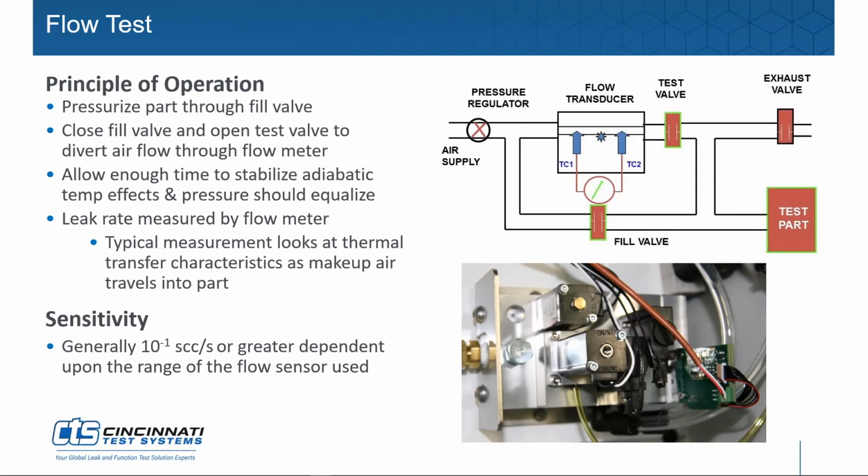And the sensitivity range of this technology is based on the flow meter range. So a flow meter that is 0.1 to 10 cc per minute has much better resolution at 1 cc per minute than a flow meter that has 0.1 to 100 cc per minute measurement, because those all have error full scale. And your resolution, the smaller your sensor is, the better off you'll be.